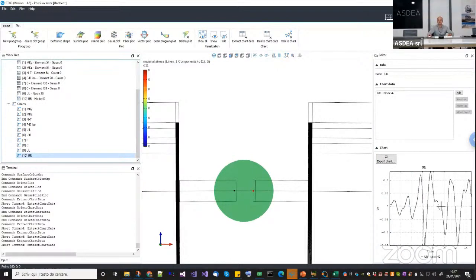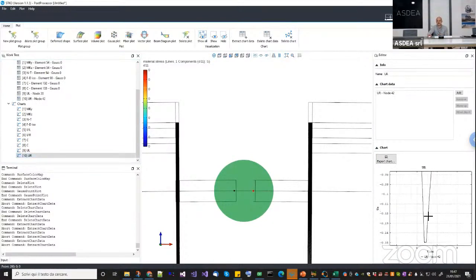And if I plot this graph, I can see that here there was a first point of contact. As you can see, it is trying to go down 0.1, but it can't. Okay, so here there was contact. Due to some convergence error, you can see that it is not exactly 0.15. Sometimes it goes back, or probably due to dynamic effect, so it pounds and then jumps back. And then the same happens on this second point of contact down here. So this is the way you can make sure that there is no compenetration.